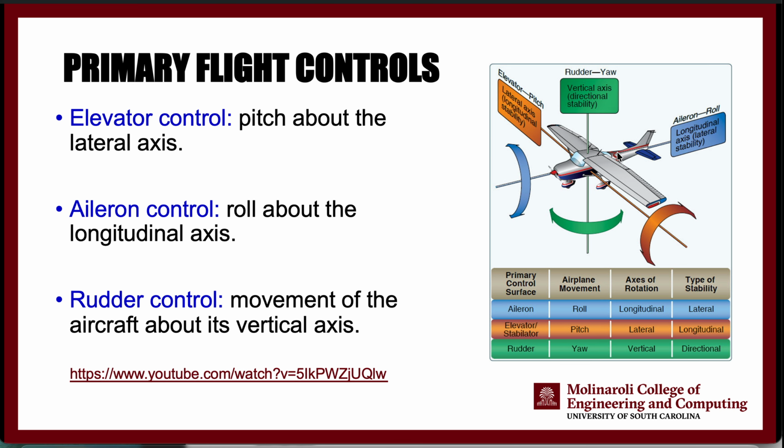There's another type of turning which we call roll that is controlled by ailerons on this axis, so movement on this axis. And ailerons are usually located at these positions on the wing. If you want to turn right, one of these is going to go up, the other one is going to go down. The same is true for turning left.